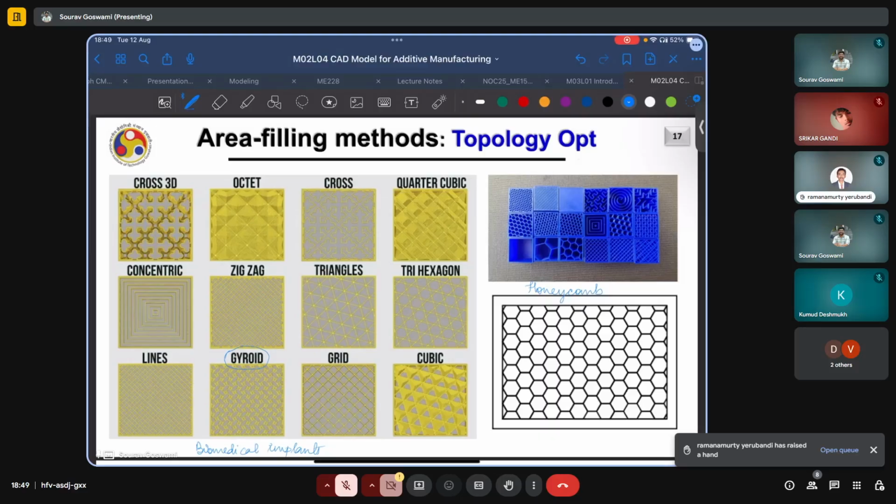And then there are these other shapes which these days come pre-built or pre-designed into any common additive manufacturing software like Simplify 3D or Ultimaker Cura, or the one which you have here is Multi Horizon. You can just simply select this from a drop-down menu, and the software will automatically fill your contour in each layer with this infill strategy.